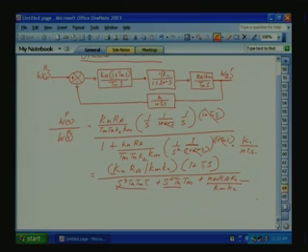constant is there. So, the S term is missing in the characteristic equation, that is the denominator. Hence, the speed control system is unstable. So, the loop should be optimized using a different approach. But if you do not do the cancellation part and if you write down, the S term will be there, all the terms will be there, that means system is stable. Now, the question is optimize it.